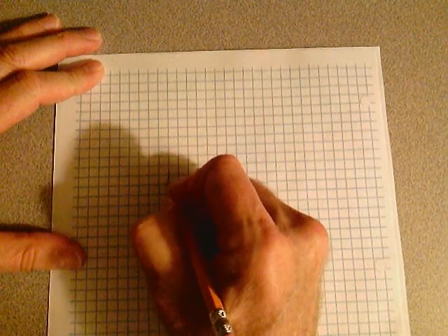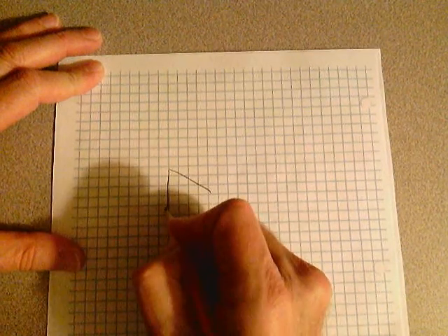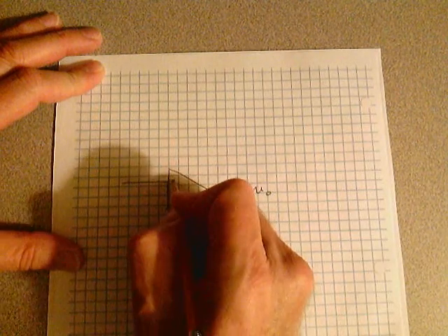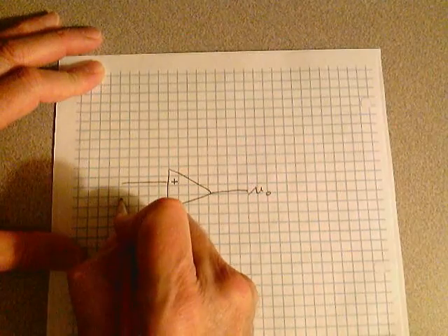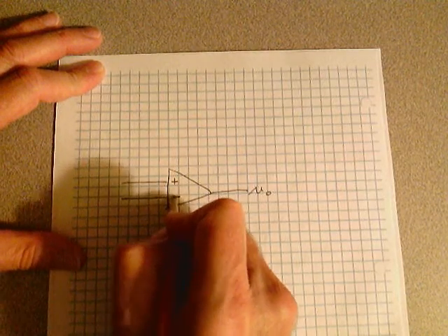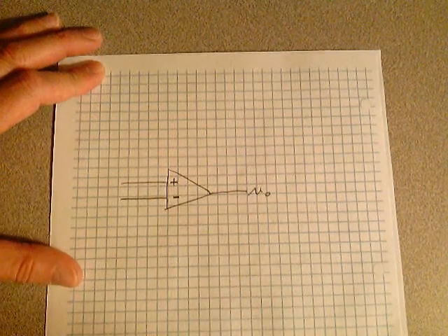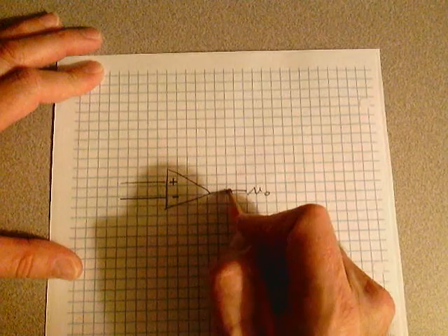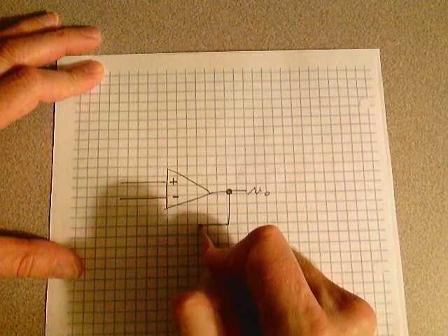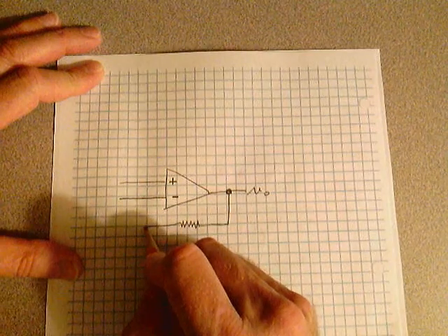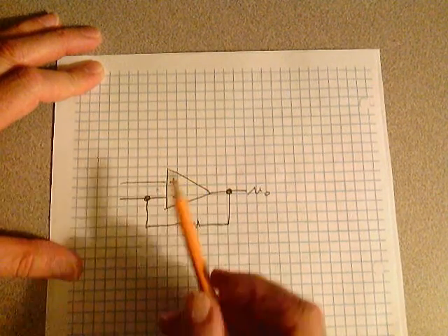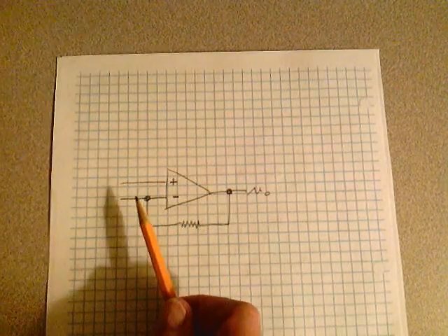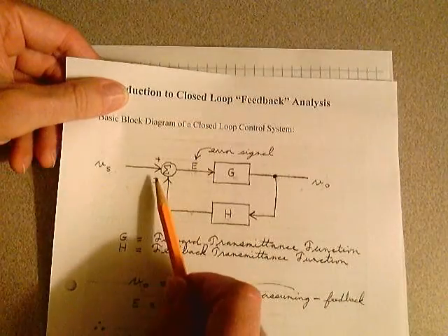We're going to have in the next lecture operational amplifiers, and an operational amplifier is going to look like that, with that being V out, and it's going to have a non-inverting input, which is the plus input, and it's going to have an inverting input, which is a negative input. It's a 2-input device. That's an operational amplifier. If you take the output or a portion of the output and you feed it back, and usually we're going to feed it back through a resistor to the input, and that input is the inverting input or the negative input. That's called negative feedback.